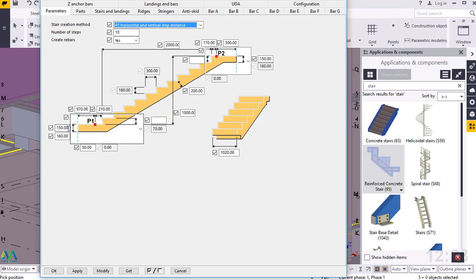So once you've done that, the thickness of this slab, you can change that to 150 millimeter, and the same you can change the thickness at the bottom end here, 150 millimeter. And the landing also, you can feed the appropriate dimension, and landing at the top here you can feed the appropriate dimension. But for our case, we'll feed here 1.35. Now I'll feed 1 there, then I'll come here and add 50 there. Then at the bottom end here, I'll leave it at 150. That's all.